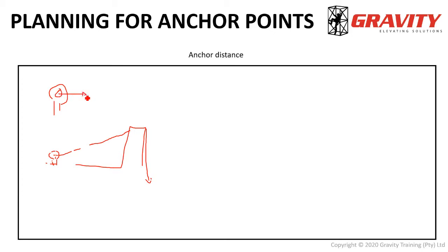Okay. Meaning sideways. Pulling straight up, we refer to as tension, sideways as shear. Eye nuts are designed for force in the tension direction, hangers are designed for force in shear direction. Okay, so the further away this anchor point is from your parapet wall, the more dangerous it becomes because you're pulling it in the incorrect direction.